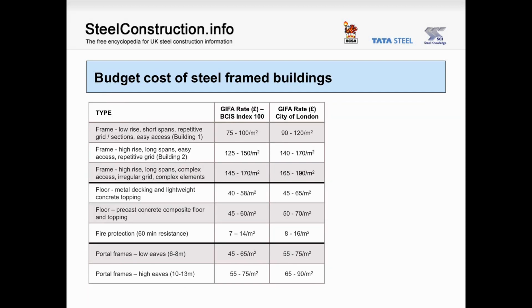One question that's often asked is, how much does structural steelwork cost? To answer this question, Gardner and Theobald published some indicative cost ranges based on actual contract values in a quarterly article in Building. For multi-storey construction, select the appropriate frame from one of the three options. Add the floor system you're considering, and fire protection, and it'll put you in the right ballpark. If you're considering a single-storey building, simply select the appropriate portal frame option.